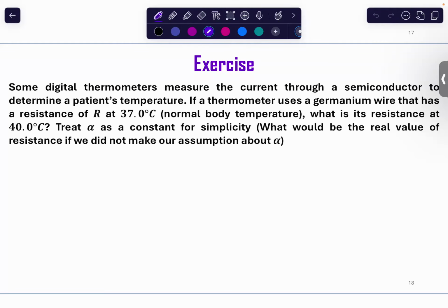But if you have a patient that's too warm or a situation that's too warm, what happens to a semiconductor if you heat it up too much? Turns into a conductor, completely destroys the reading. So we can't always just take these alphas, these unique numbers for a material, as always going to be constant. Again, when you're solving homework problems for a 100 level class, just use what's on the table, but I'll show you what happens otherwise, because we are using germanium.